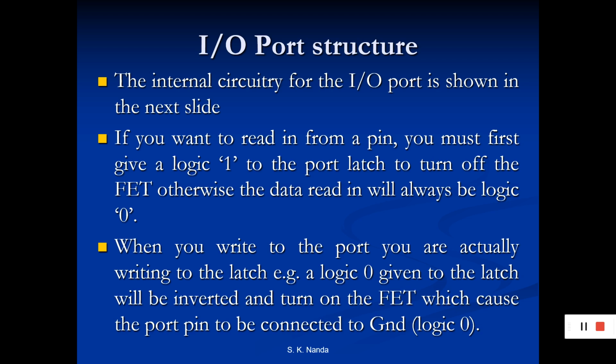For input output pin, all the circuits within the microcontroller must be connected to one of its pin except P0 port because it does not have pull-up resistors inbuilt. For input pin, logic 1 is applied to a bit of P register. The output transistor is turned off and the other pin remains connected to power supply voltage over a pull-up resistor of high resistance.